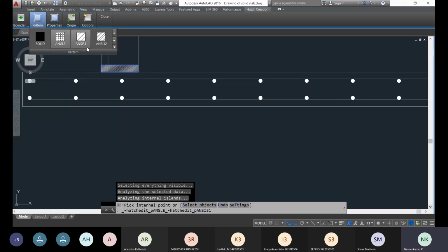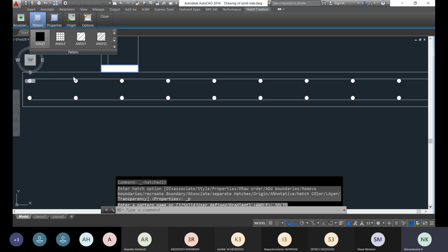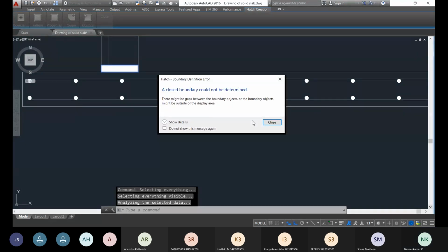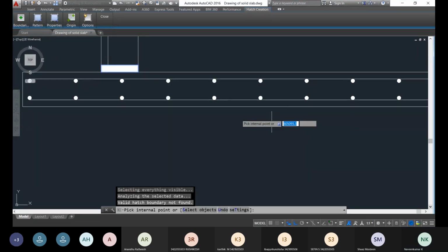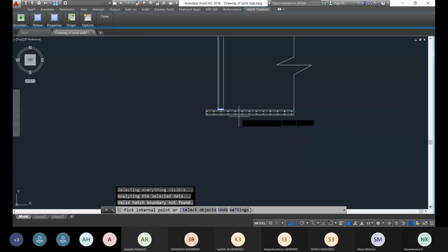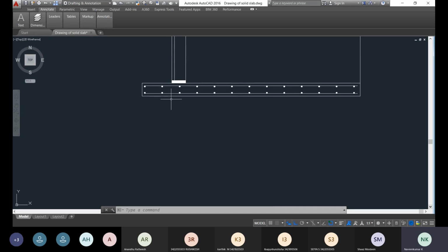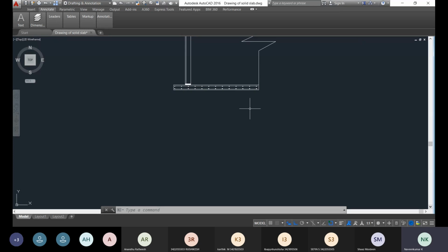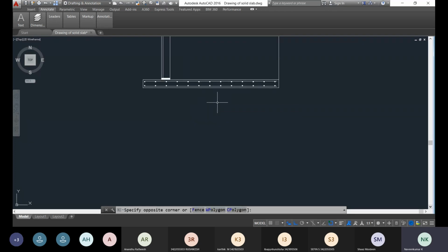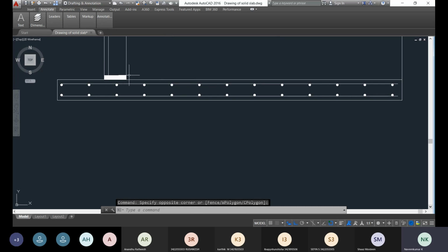For us to provide the connectivity, solid pattern is much better. Okay, so you choose the solid pattern. So it provides the connectivity between the base as well as the wall of the water tank actually. Now you can move the base to match this point. Okay, so why? Because the base should be in this level.